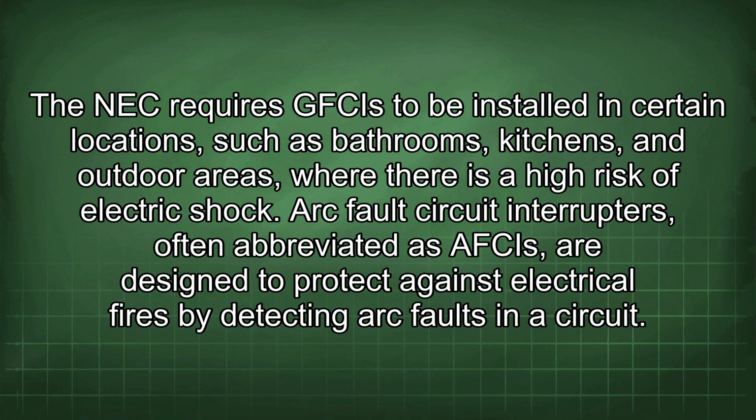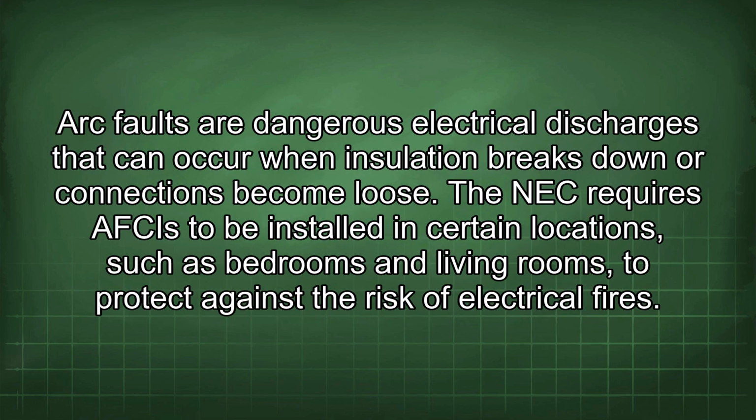Arc fault circuit interrupters, often abbreviated as AFCIs, are designed to protect against electrical fires by detecting arc faults in a circuit. Arc faults are dangerous electrical discharges that can occur when insulation breaks down or connections become loose. The NEC requires AFCIs to be installed in certain locations, such as bedrooms and living rooms, to protect against the risk of electrical fires.